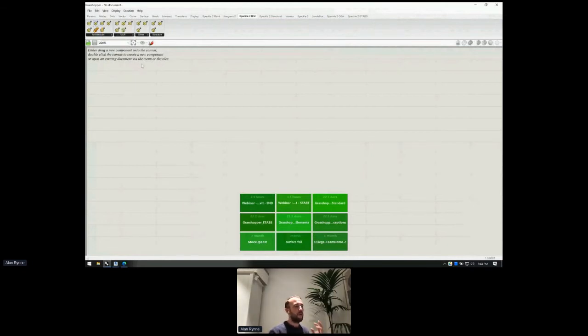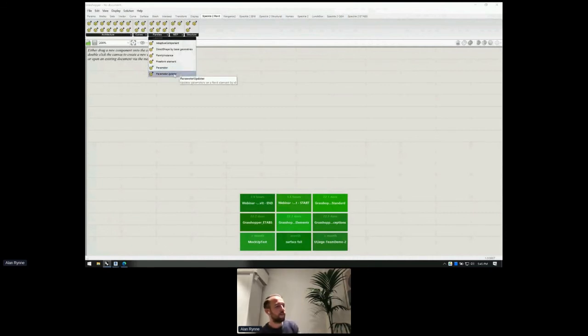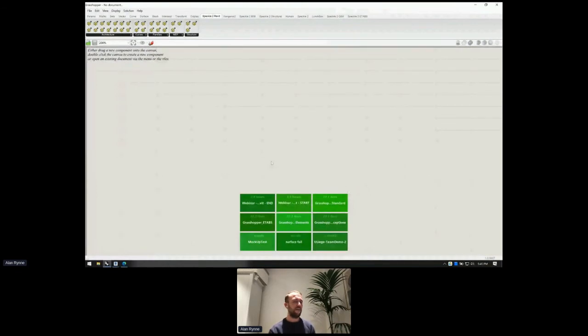And if you want to really target Revit in particular, we provide another tab called Speckle Revit, which contains specific Revit commands and nodes for you to specifically send things to Revit, which may include creating walls with specific parameters and other nice things like placing family instances, creating free-form elements, or even updating parameters directly from Grasshopper. So instead of sending geometry, you can send update instructions. So some parameters will be updated with the values that you specify. And hopefully we will get time to see all of that, but I may go a little bit fast. Feel free to stop me.